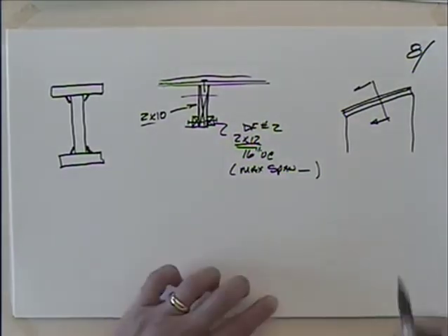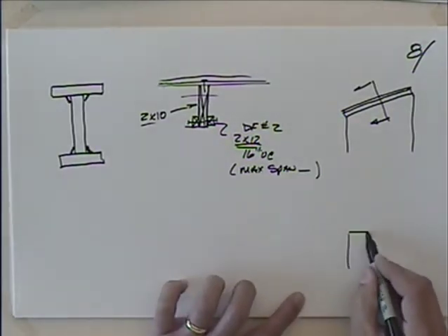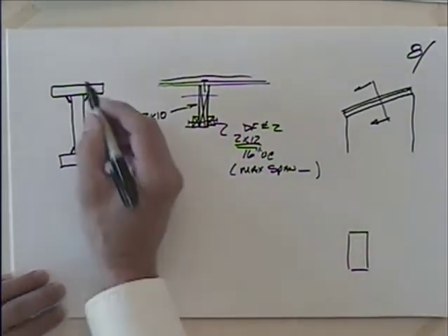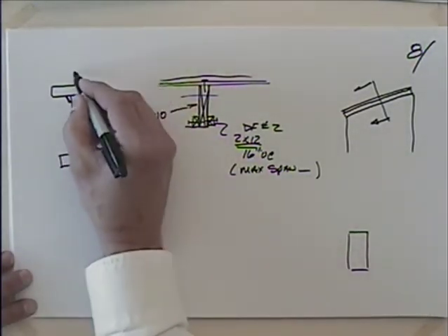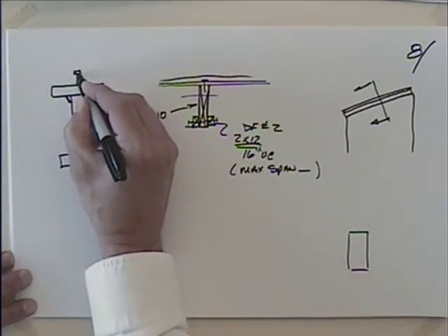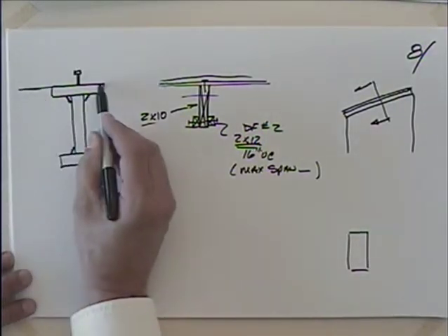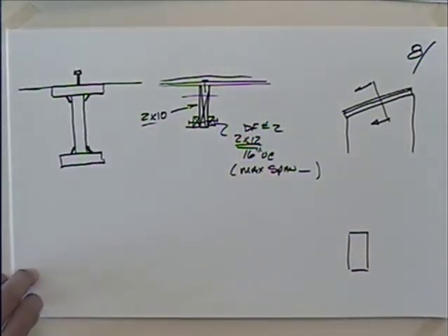And the concrete guys will get into this quite a bit. You take a beam, maybe an I-beam, like this one, and what you're going to do is they're going to weld a stud onto this great big glorified nail. It's about 1/2 inch or 3/4 inch in diameter. And then when they come in here and they pour concrete on this, that's how this floor that you're sitting on is made.